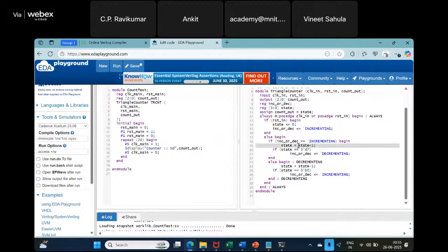Okay, it blocks. So this equal to means the simulator will wait for this to complete and then go here. But if you use non-blocking, right, it will increment 6 to 7, but right away it will go here. Okay, that is why it has to be 6. So if you are using non-blocking, use 6. If you are using blocking, use 7.